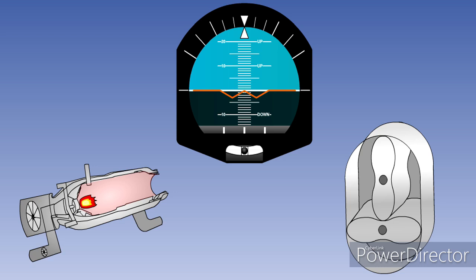On some aircraft, where air from the engine compressor is not available, such as on large pressurized piston engine aircraft and some turbopropeller types, blowers driven by the engine are used to supply air to the air conditioning and pressurization systems.